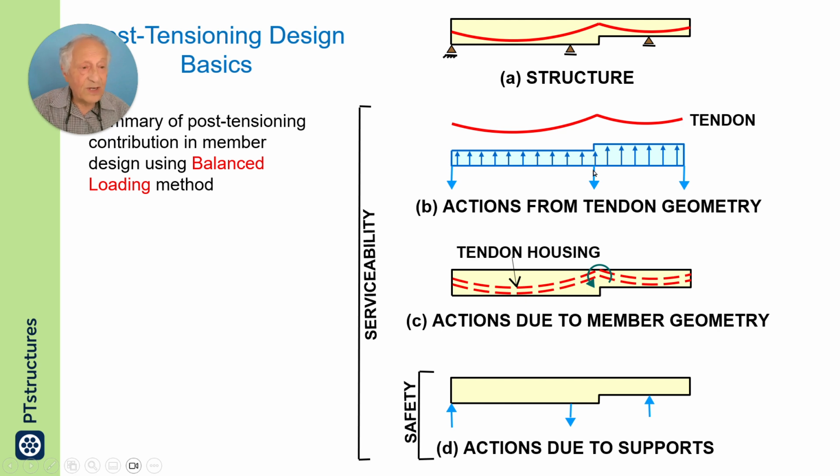But if you recognize that there is a change in section and there is also a bending moment, combination of this and this will be, so to say, extended load balancing, and will be used to calculate the deflection and the possibility of crack formation.